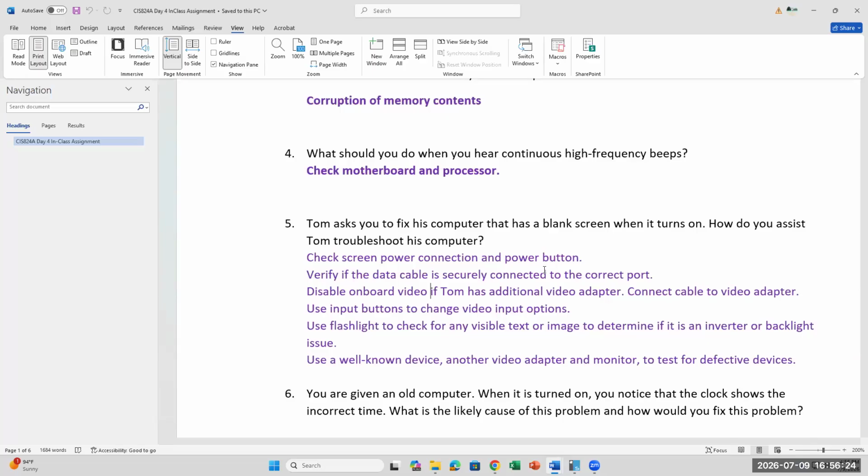But you can see the keyboard, the power is running. So what I did was I took my laptop, plugged the HDMI cable to a monitor, and I can see everything. So that means that my screen is bad for sure, right? And then I have to replace my screen. And sometimes, when you slam your screen shut, or you move things around, you drop your laptop, dropping a laptop definitely can damage screens. And sometimes the hinges are connected to the sensor or the actual power source to the laptop. Some of them are like that, then they can get damaged as well over time.